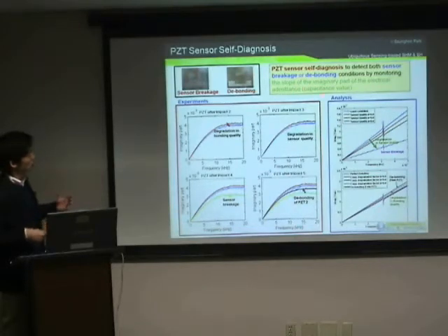Actually, this work is from a collaboration with Dr. Park at Los Alamos National Laboratory. So this is a very important issue because sometimes the sensor is broken or debonding between PZT and structure occurs. So we need to check whether the sensor is working well or not before health monitoring implementation.